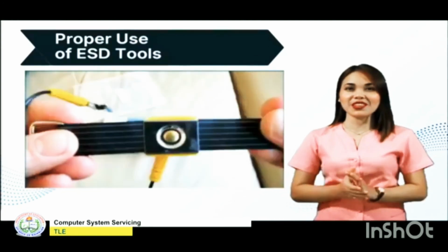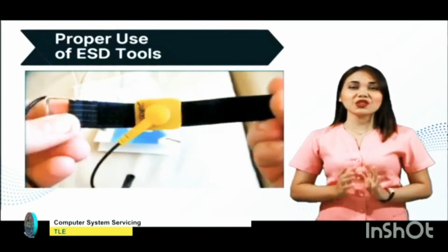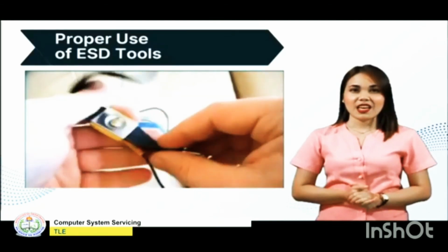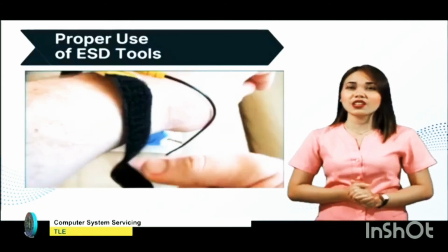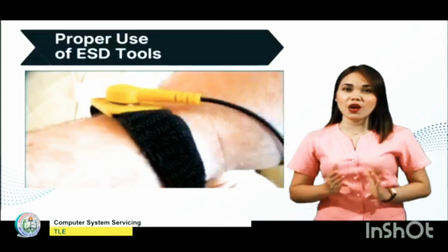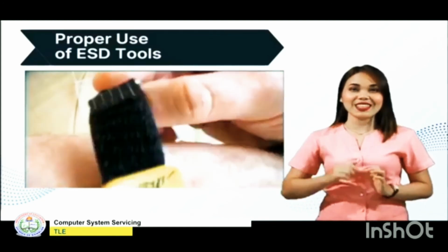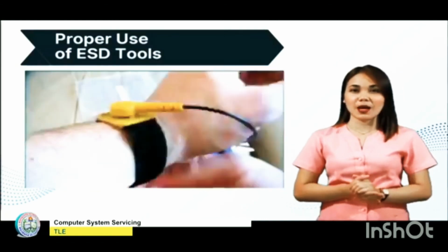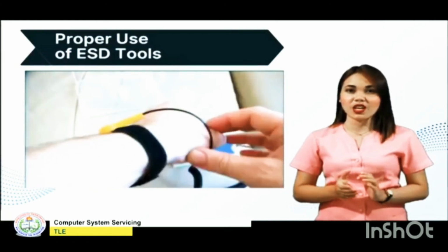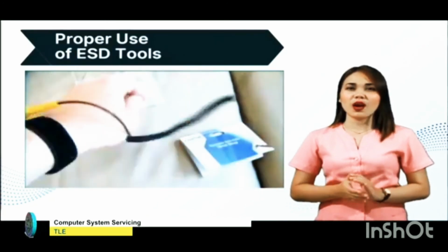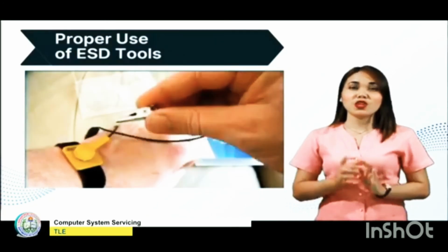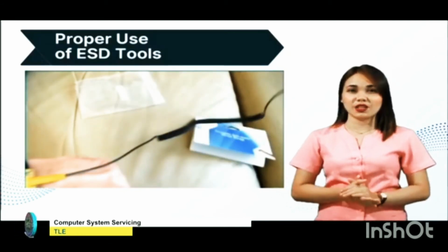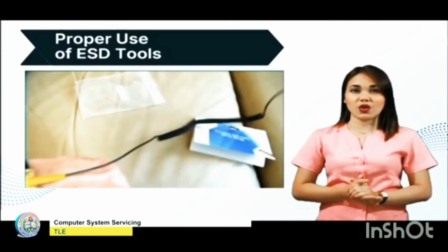The purpose of an anti-static wrist strap is to equalize the electrical charge between you and the equipment. It is a conductor that connects your body to the equipment that you are working on. When static electricity builds up in your body, the connection made by the wrist strap to the equipment or ground channels the electricity through the wire that connects the strap. Reducing the potential for ESD will lessen the likelihood of damage to delicate circuits or components.